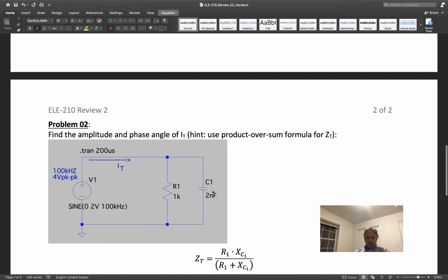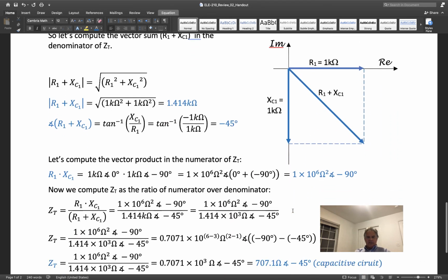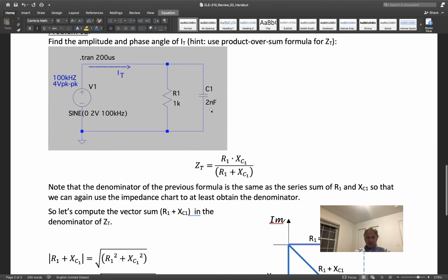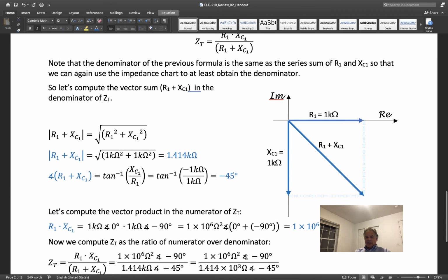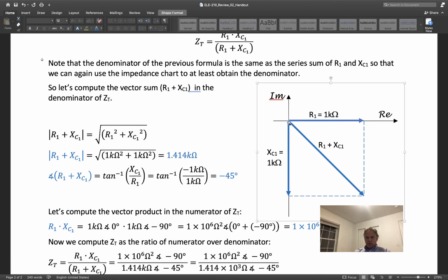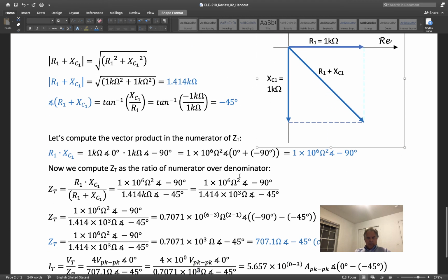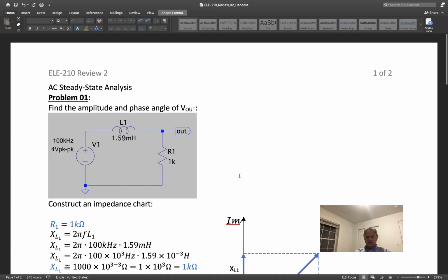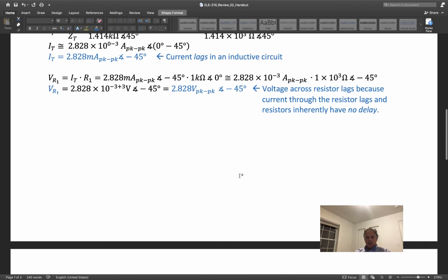I will, like I said, I will get you the correct value here so you can kind of see how that all works. But for now, we're just assuming that whatever this capacitor is, it has 1,000 ohms of capacitive reactance. And of course, capacitors point straight down at minus 90 degrees. Inductors point straight up at plus 90. So there's our kind of review of our basic steady state analysis, and I hope that helped.